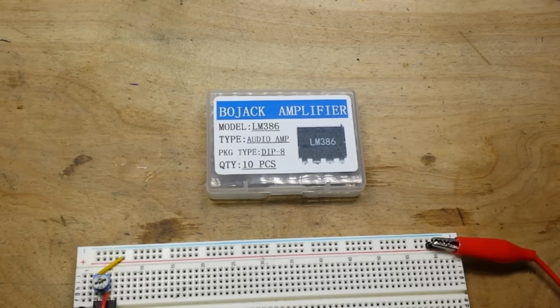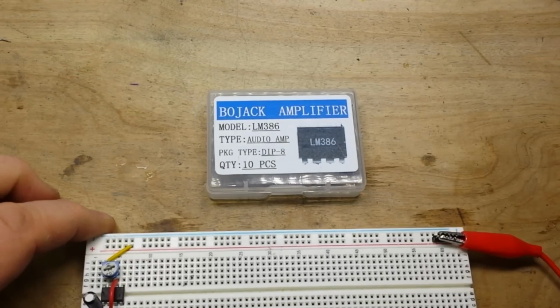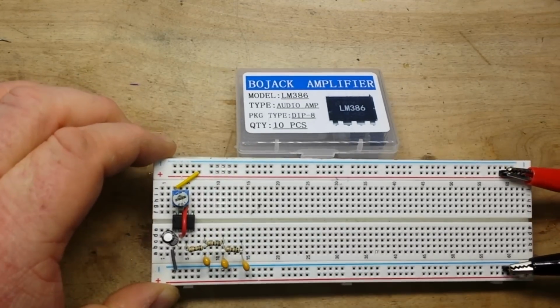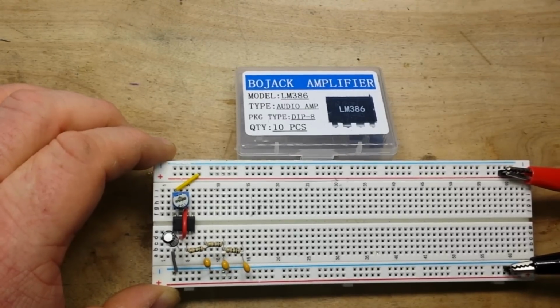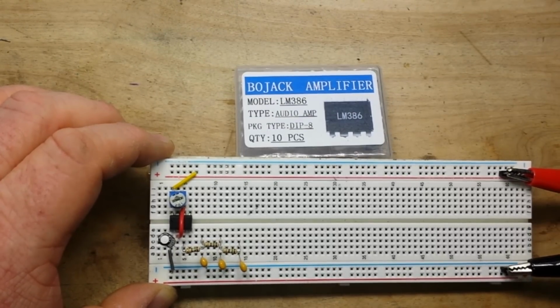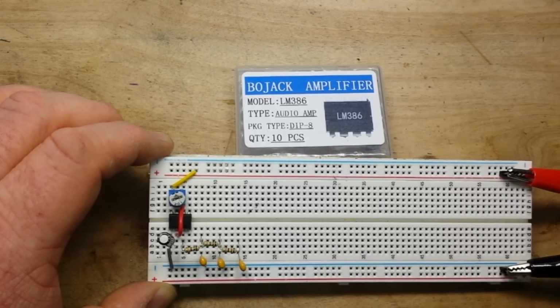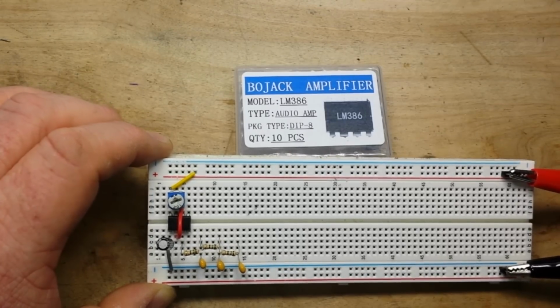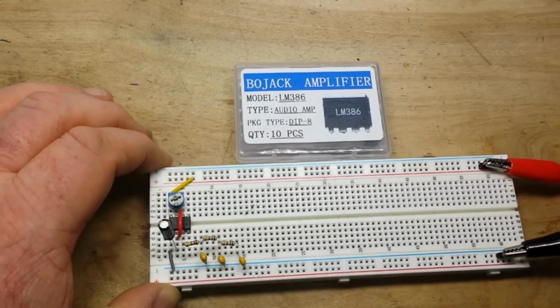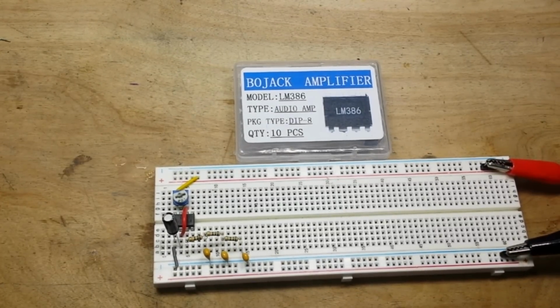So the first thing we need to do that is we need an audio source. I got all kinds of options for audio sources, but I like to keep things simple. And if you've been watching the channel for a while, you know my favorite IC of all time is the 555 timer. So I have set up here a simple bistable, I'm sorry, astable 555 timer, and it is oscillating at about 1 kilohertz, which we can take a look at here.